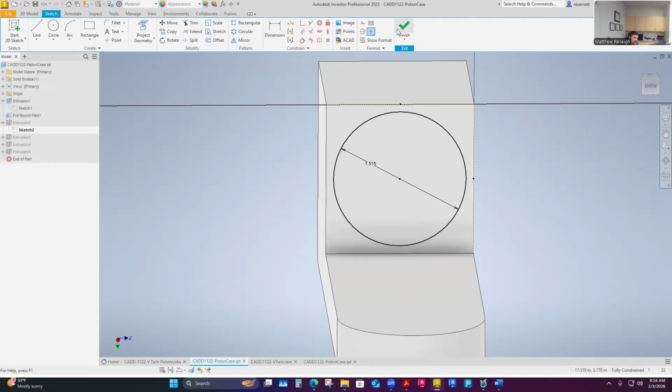And I'll finish that. Yeah, mine's 0.015, that's 15 thousandths is how I'd read that. But yeah, that's about how big I had to go. That's really big. Like I said, if it was metal, it might be 2 or 3 thousandths. I actually don't know what the tolerance for piston to cylinder is.